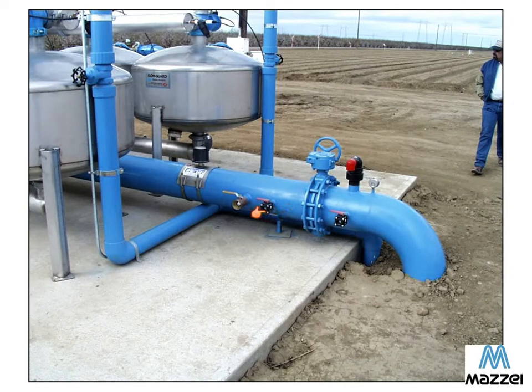So our recommendation is to put in valves sized to accommodate the larger injectors, to be able to utilize a lower differential to activate the injector. This should have probably 3-inch entry ports, so a 3-inch injector will operate to obtain the desired suction capacity.